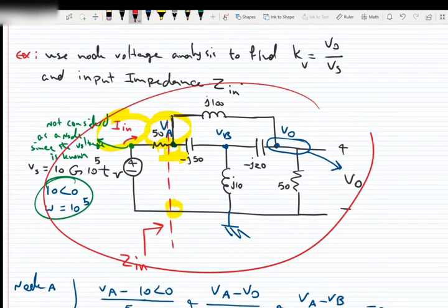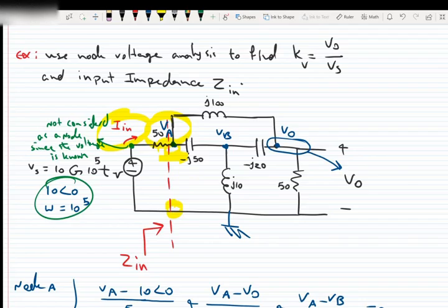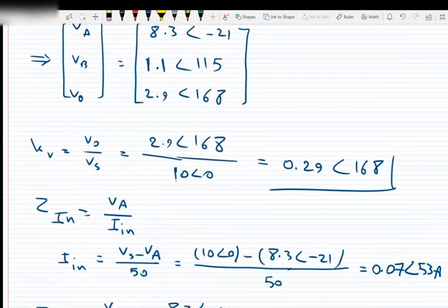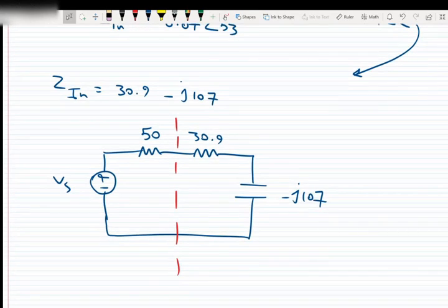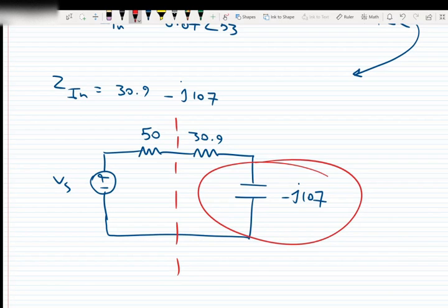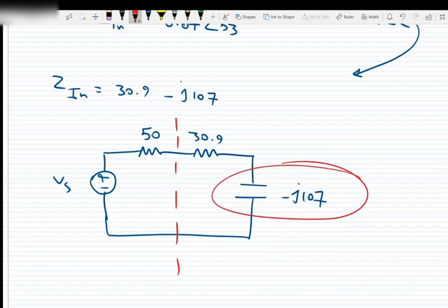You see that we don't have any inductor in this equivalent circuit because inductors and capacitors cancel each other, and the capacitor in total was stronger than the inductors in this circuit, and then gives the capacitive reactance at the output.